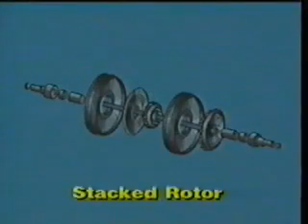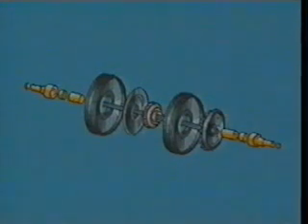Stacked rotors consist of a stub shaft for each end, several impellers, a balancing piston, spool pieces, and other needed parts, all held together with a heavy center bolt. Although this type of rotor is always used in a stacked style, vertically split casing, it can also be used in other types of casings as well.